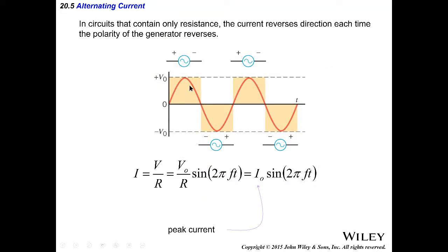Well, in a circuit, if you have this voltage, then the current is simply directly proportional to it. The resistance is not a function of time. Resistance is whatever the resistance is due to the material you have made this wire out of. It has a definite resistivity, it has a definite thickness, cross-sectional area, and you already have a certain length L. So the resistance is not a function of time. Therefore, the current is in phase with the voltage. When the voltage is big, current is big.